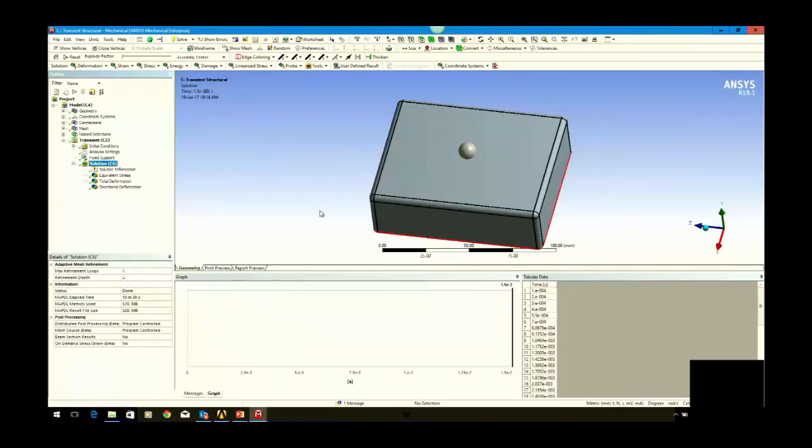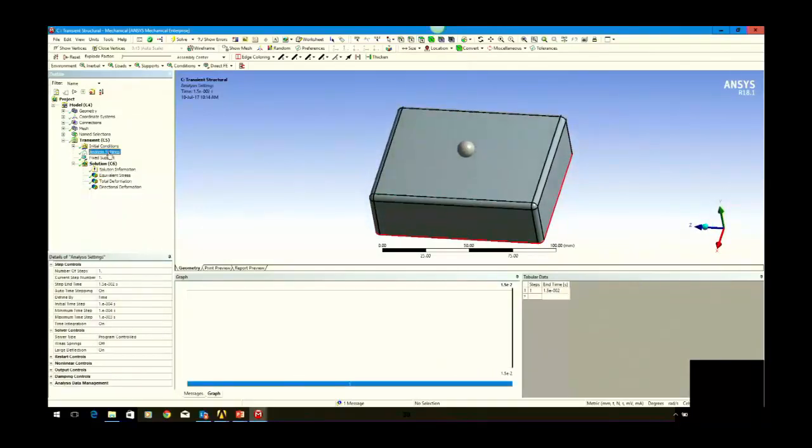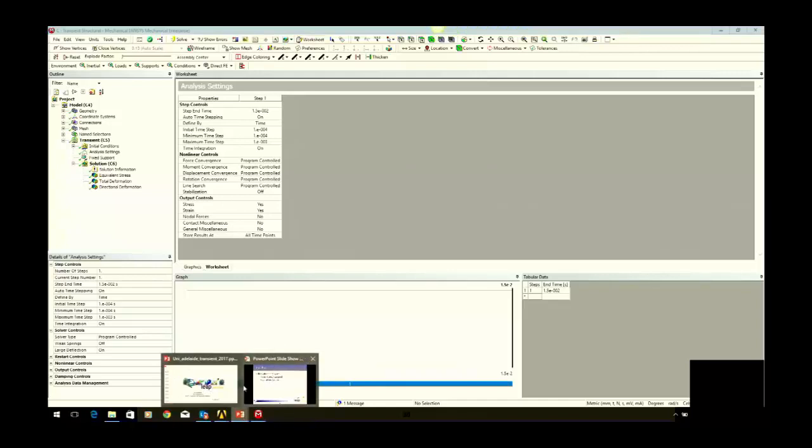But when you have a lot more non-linearities involved, sometimes you need to switch to an explicit solution. Here this is quite easily done with an implicit simulation. The total duration of this event is quite short, it's 1.5e-2. We're only really interested in the impact, but if we're interested in the bouncing around, then we might need to solve for a longer time.